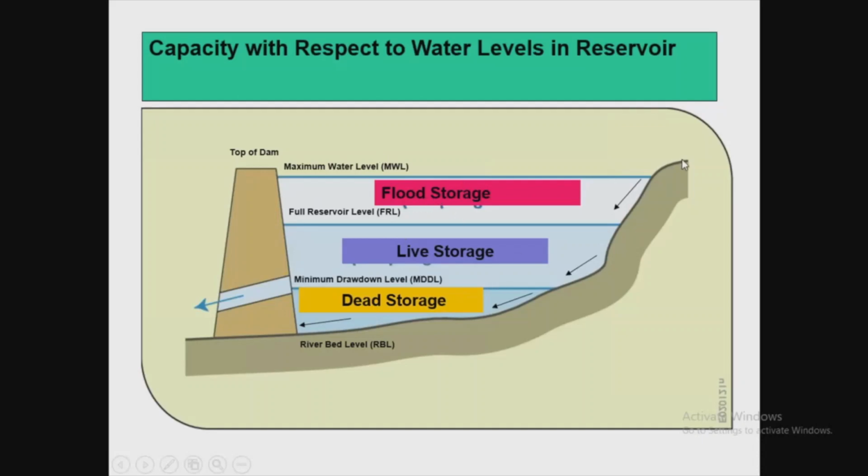And that's why, when flowing water comes into contact with still water, sediment drops down, because the sediment carrying capacity of the river reduces. Every river has some carrying capacity. So whatever the carrying capacity of the river is, because of the reduction in velocity, whenever flowing water comes in contact with stored water or still water, it loses its sediment carrying capacity. So it drops the sediment.